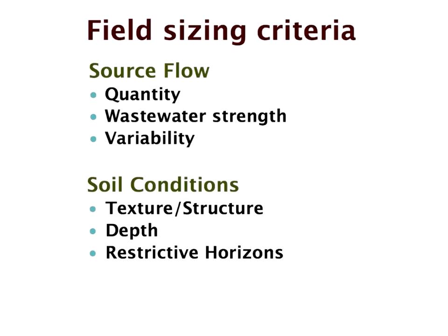With primary effluent, the risk is the buildup of an anaerobic zone around the dripper because of lack of oxygen. With secondary treated effluent, that risk doesn't appear to be there.